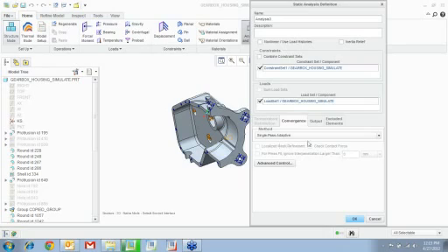Now you see that if you have an assembly, you can do localized mesh refinement. If you do contact analysis, you can check for contact force. And if there is any interference, then you can check the press fit and ignore the interference over there as an interpenetration.